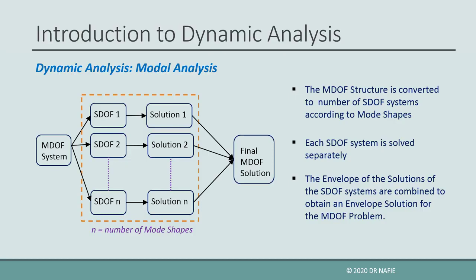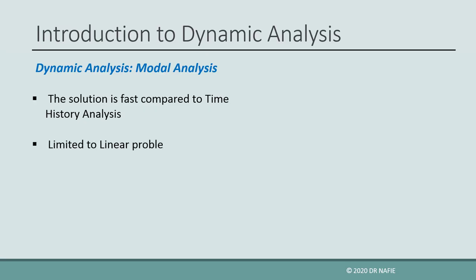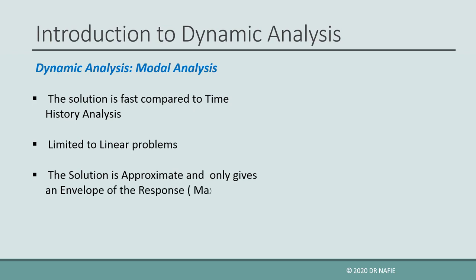The idea behind this method is to make the solution faster. For larger problems, this method becomes extremely fast when compared to time history analysis. Modal analysis, however, is limited to linear analysis. The method is also approximate and only provides an envelope of the behavior. We can estimate the maximum and minimum values of the displacements and internal forces, but the method does not provide us with a complete behavior of the structure over time.